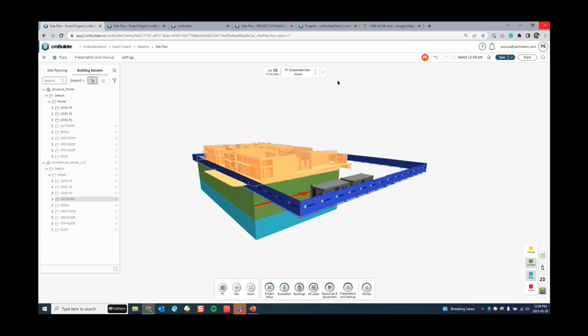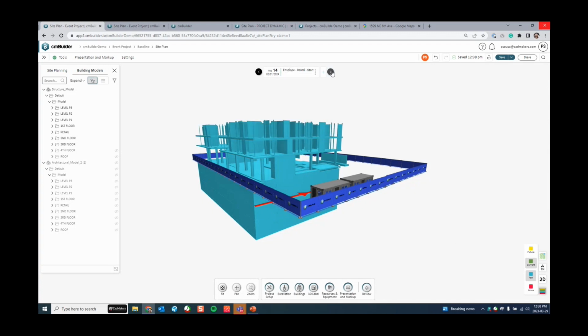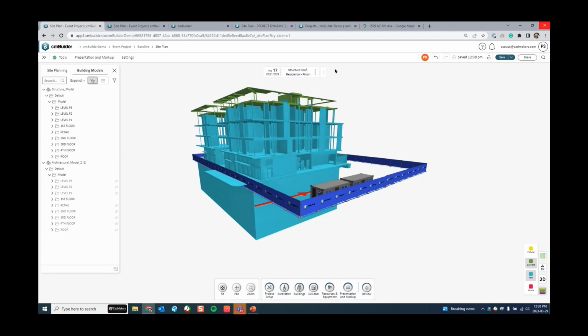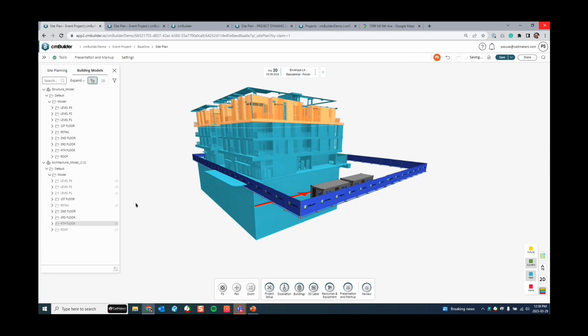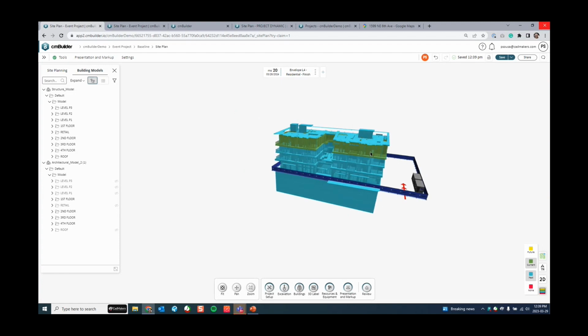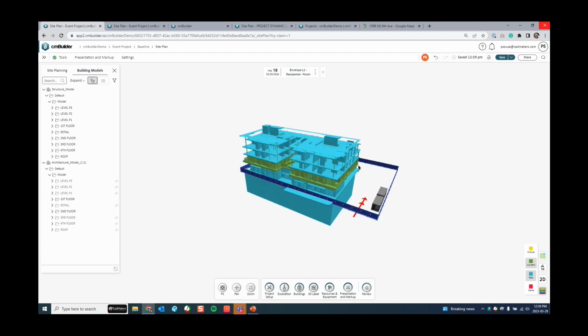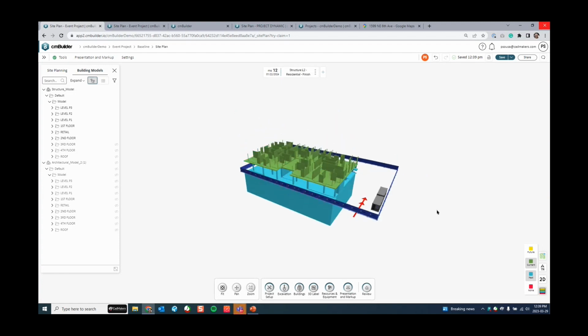Cool. I could also go into the milestones in which they are going to be executed and select them over here. Say for this stage, envelope 2, I can right click, begin from this milestone, use my shortcut to go forward, right click, begin to this milestone, shortcut, select Control B as a shortcut, go forward, envelope roof, Control B, and then go forward, right? So now I have a very interesting way to visualize what's going on in each one of these points in time.